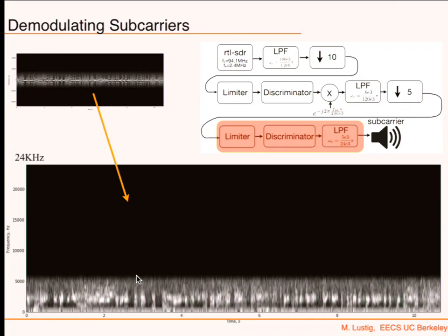Why is 5 kilohertz not enough to give you high quality audio? Because when I talk, I'm sure I only use like 2 kilohertz of bandwidth. No, really, the majority of the amplitude is in the 2.5 kilohertz. But it sounds like talking on old phones, because they would filter up to 5 kilohertz. It doesn't capture everything, so it reduces the quality. Music doesn't sound as nice, because music goes into higher frequencies.